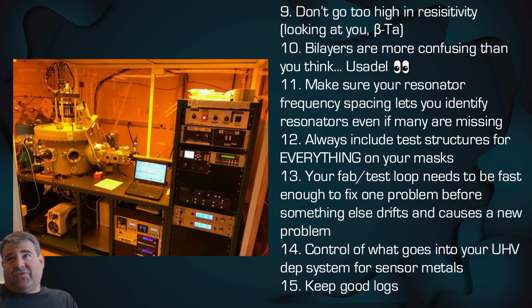You always should include test structures on your masks. Things go wrong all the time in the fab. It's the hardest thing we do. The test structures will help you figure it out.